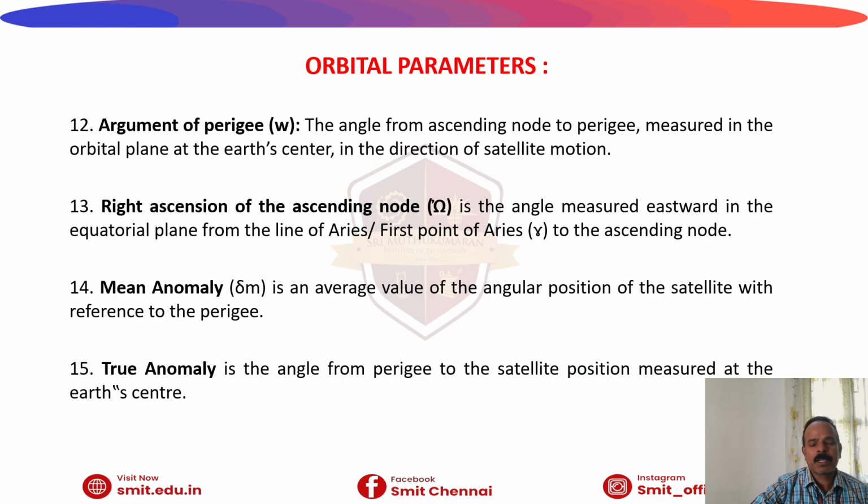So these are the vitally important parameters that decide the position of the satellite. If any deviation occurs, it should be controlled from the Earth station by sending pulses through the jets. Even a 0.1 degree tilt can change the communication characteristics of a satellite, not only in the Earth antenna but also in the satellite antenna. So both antennas should be kept intact without any deviation. Even a 0.1 degree tilt per year will accumulate and make a huge difference in the communication satellite.